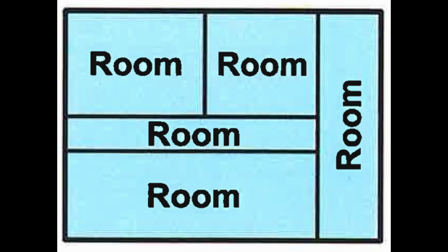Section 1. Understanding the terminology. Before we begin modeling, it's important to clarify the terminology. Revit uses 4 closely related concepts: rooms, areas, spaces, and zones. And although the names sound similar, each one serves a very different purpose. Rooms belong to the architectural workflow. They represent habitable spaces and store information like finishes, occupancy, and usage. They also provide floor area, perimeter, and volume data.